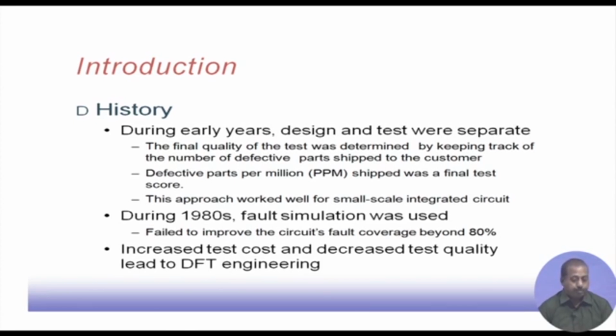That way we get some idea about the quality of the test vectors that are applied. We try to do some modification to the test vectors, so that this coverage improves, but getting coverage more than 80% was difficult. In our introductory classes we have seen that even with 90% fault coverage, there is a huge loss in the number of defective parts that are sent.